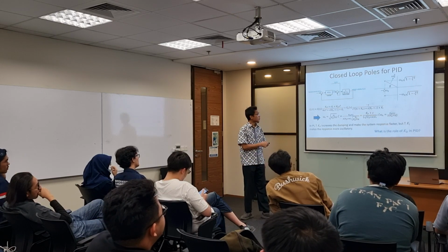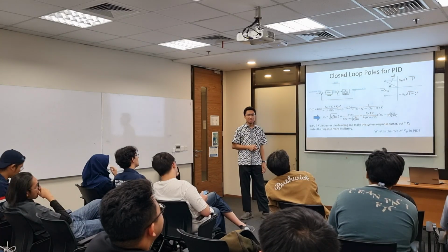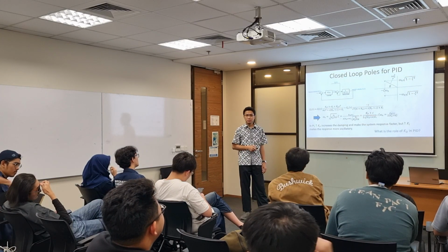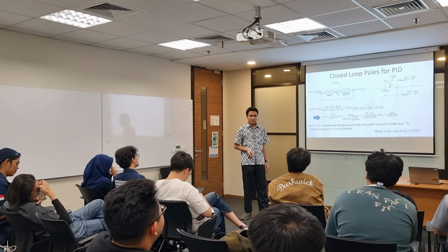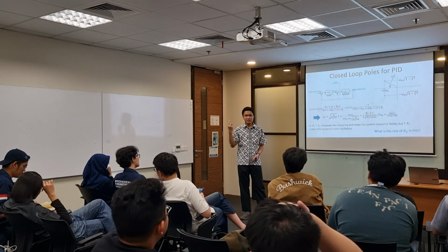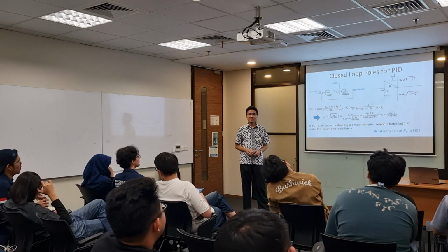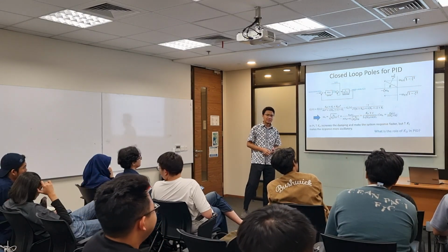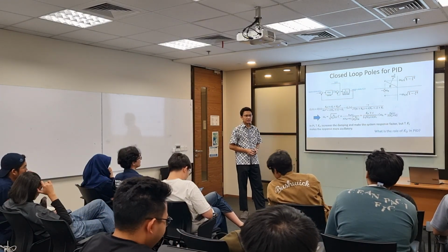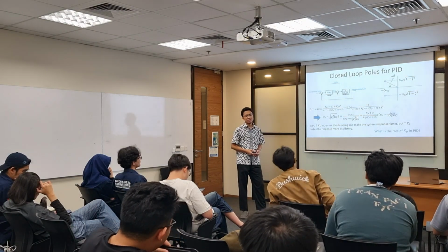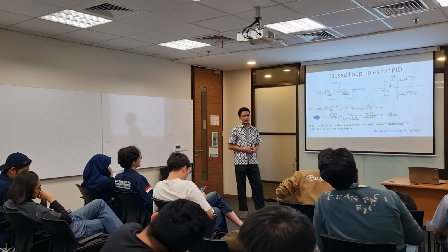Have you tried out the system with PID? Not yet. You can simulate, or you can calculate, or just you are imagining the role, is it? Well, it is not. No, PI already has zero steady state error, so no need derivative to do that.